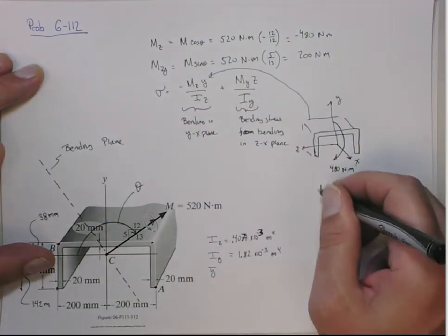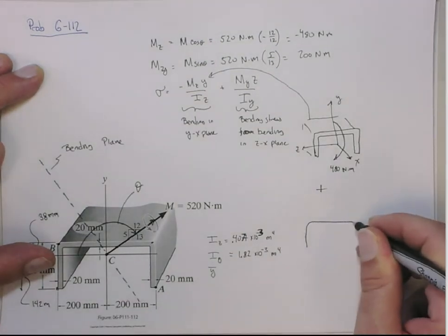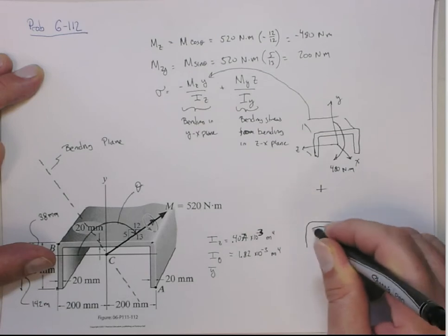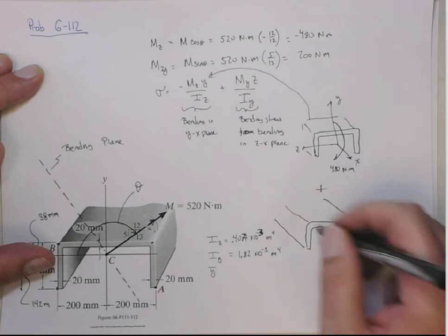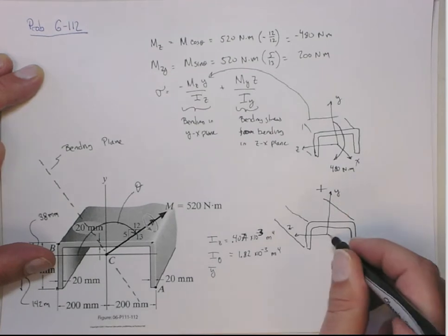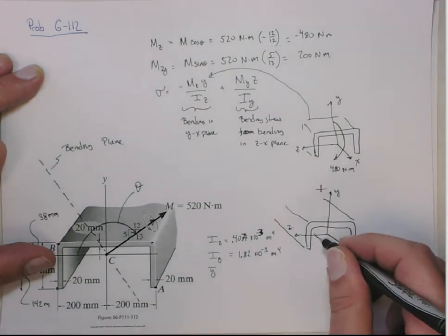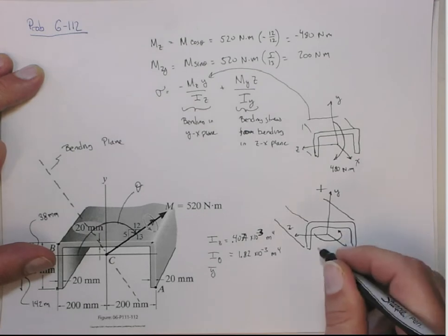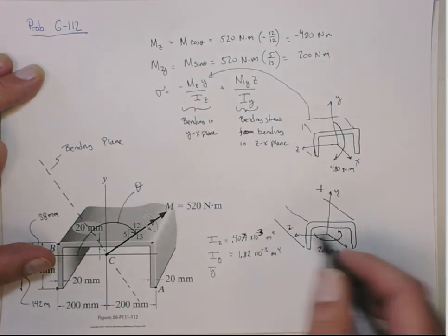And then we're going to superimpose onto that the stresses that we would get. Same cross-section. It's the same picture. Z-axis, Y-axis, X-axis, but then a positive 200 Newton meter bending moment around the Y-axis, or in other words, in the ZX plane.